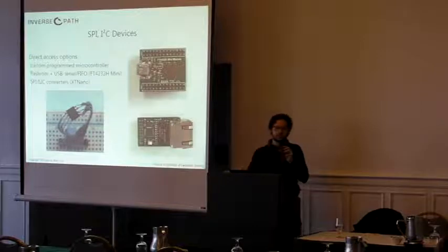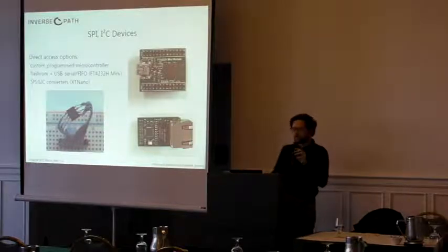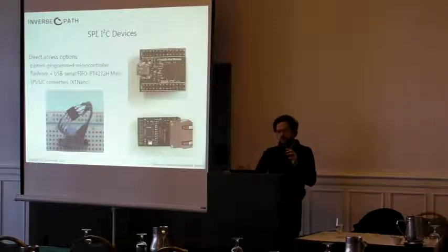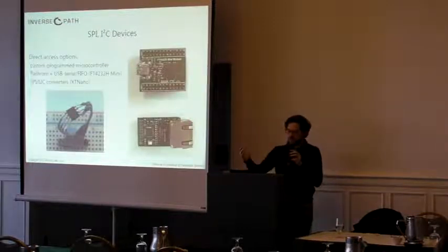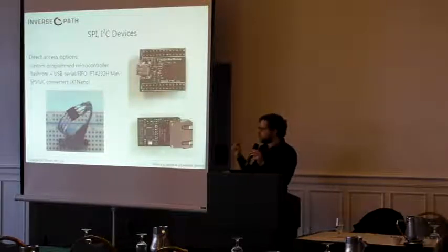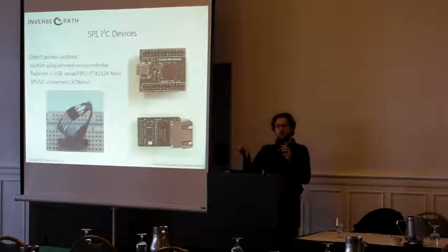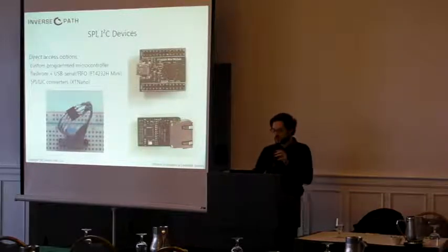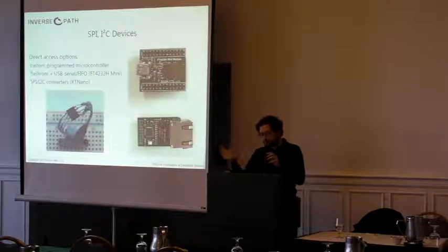So you can use these kinds of converters, and you manually connect your chip to them, and you get access to the chip. It's very, very easy. If you can desolder the memory, it's fairly easy. And most of the time you will have test points on the board that allow you to read the memory without having to desolder it.